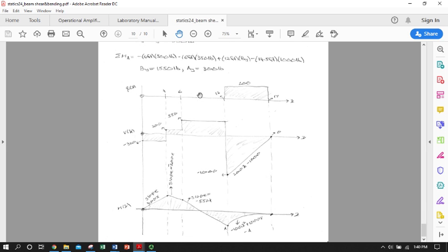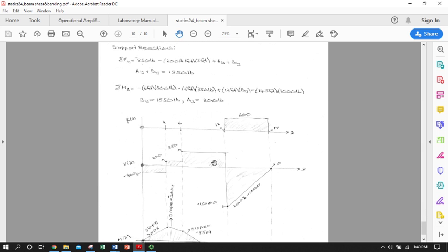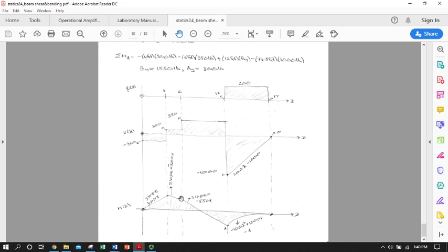So the limits of integration from our algebraic solution up here effectively just become the handoff points to connect these curves on the graphical method. But this is a very easy way of finding maxima and minima. If I were just trolling effectively for where's my maximum shear, it's real easy, especially if you draw these to scale. And if I wanted to know my maximum moment, I'd be looking at either this point or this point, and probably looking at both of them as being pretty big.